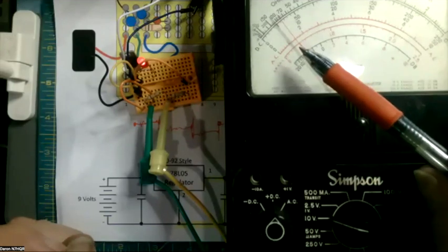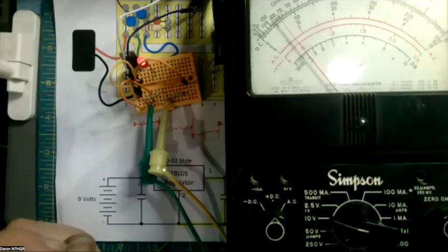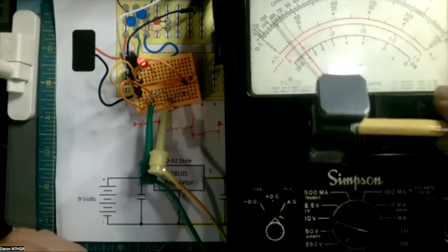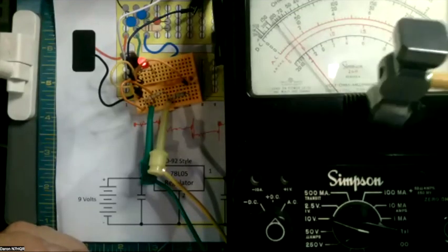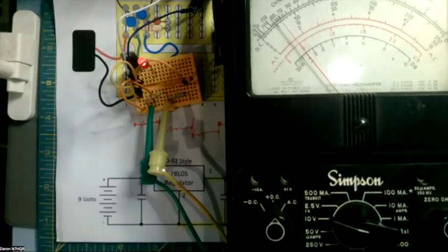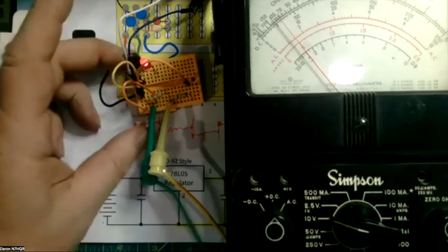1.4 volts. And we just measured it with the digital voltmeter at 2.5 volts. What's wrong? Can anybody tell me? Is it just the difference in the meters? Difference in the resistance in the meters. Yeah, this meter is what's called a 20,000 ohms per volt.